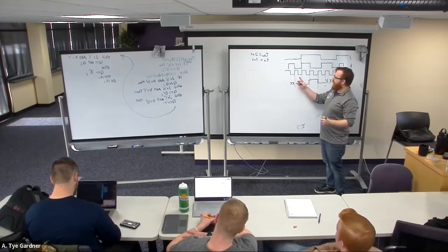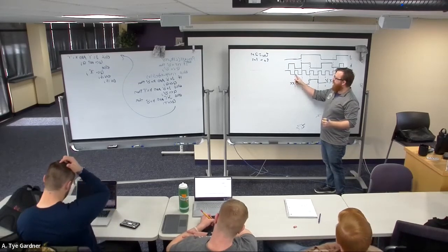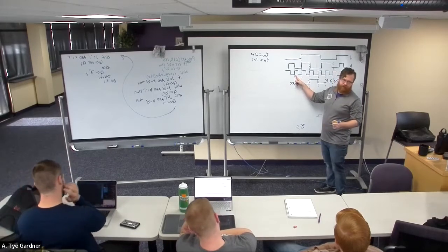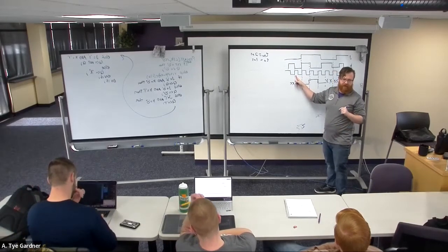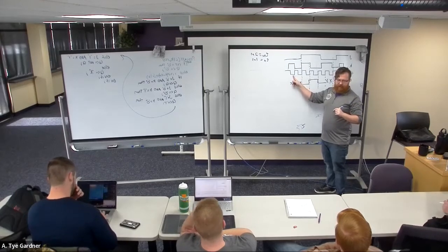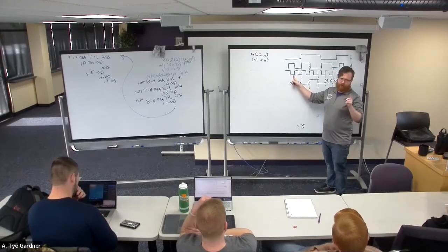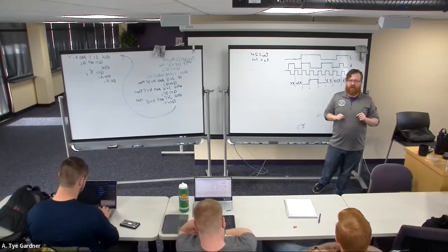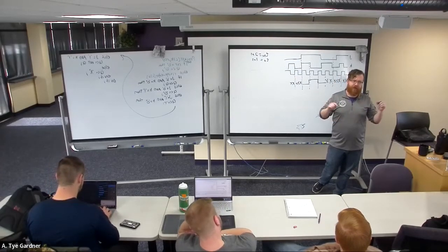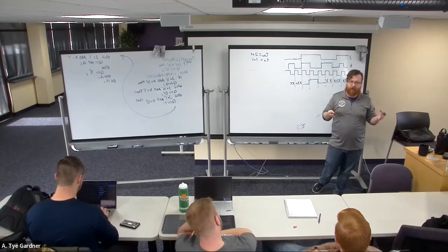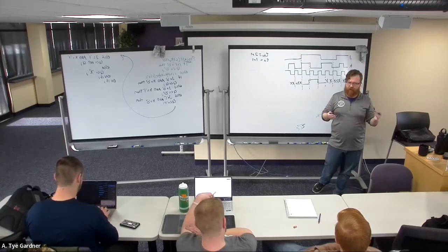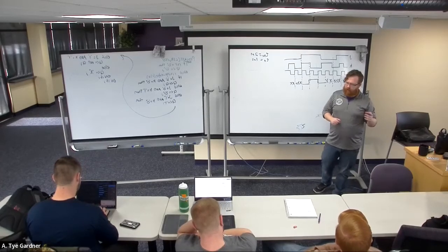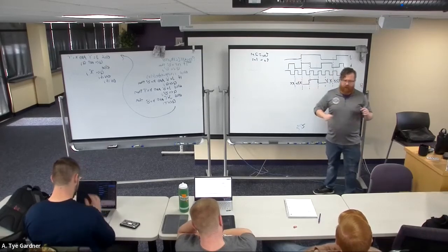You'll have to look and see, is this falling edge 2 nanoseconds before one of the input signals changes? That's the setup time. And does it stay the same signal 1 nanosecond for the hold time after the clock changes? The setup and hold times are how we determine if the signal is stable before we clock in the value. Okay. So keep aware, if it's exactly the same time, there's going to be a problem.